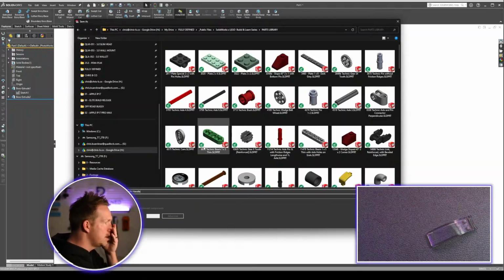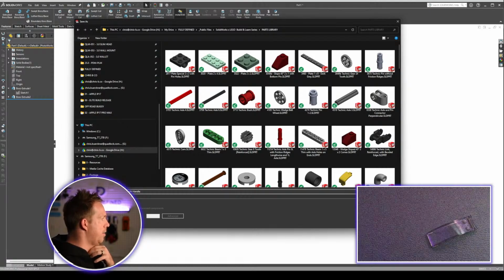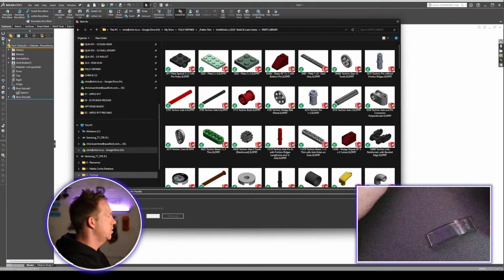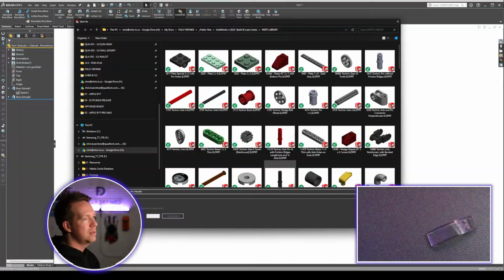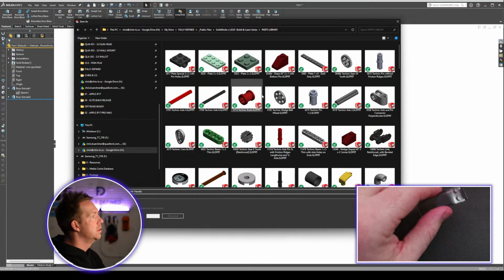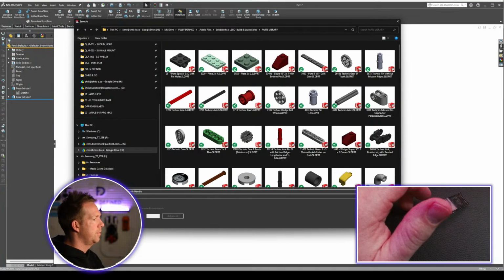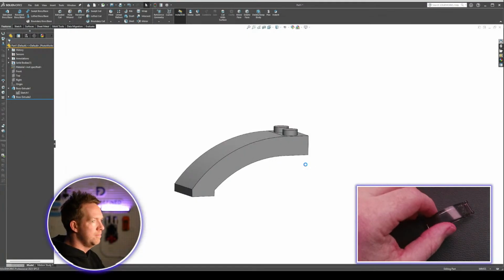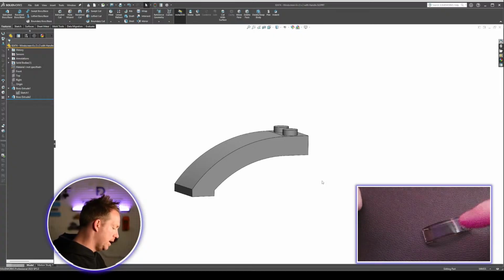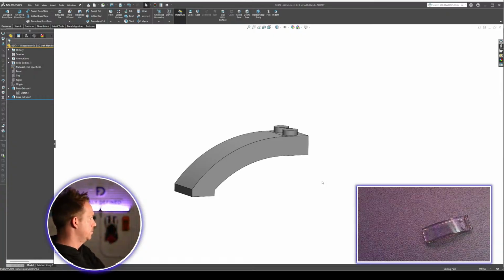And in the parts library, you'll see some parts saved with different colors, but where I'm at now, I don't save different geometry for colors, we do the colors as configurations. So you'll see plate 2x2, and that'll have different configurations for that part. So save this one, and then let's keep going. The next step is going to be the shell.